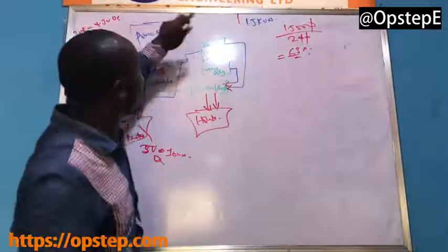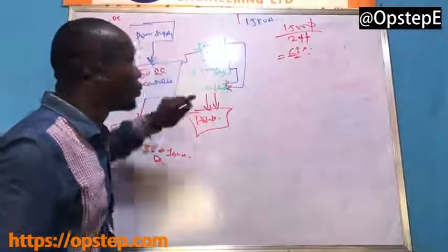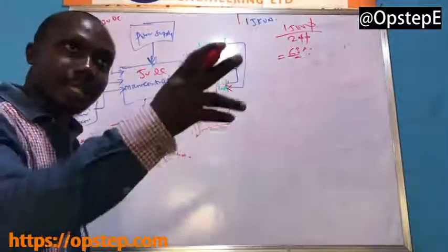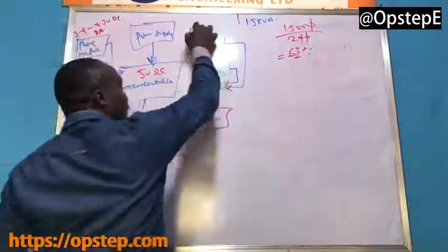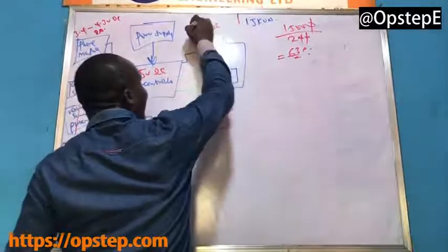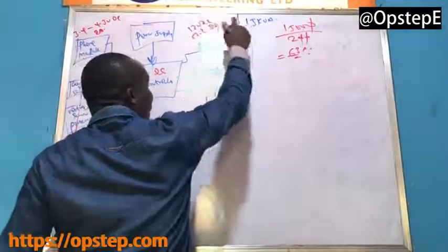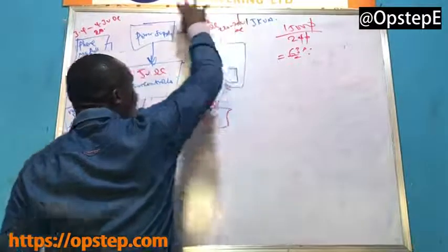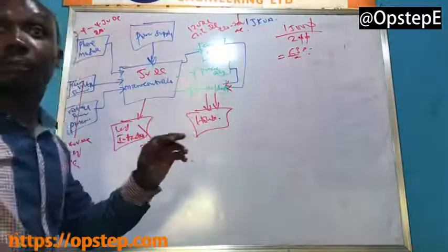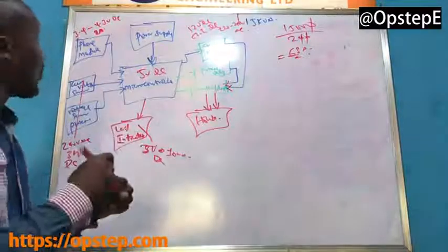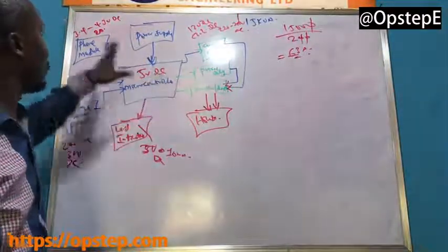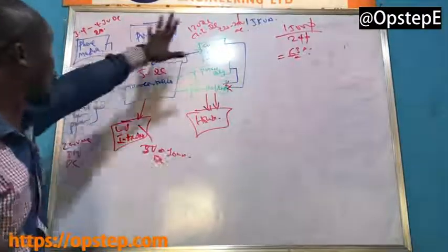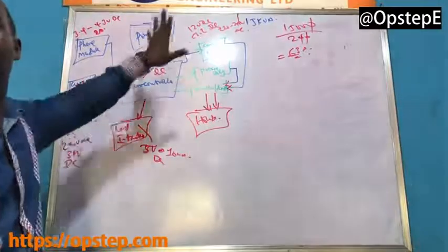For your generator relay, your NEPA relay and the enable relay, it uses both AC and DC. The coil is DC at 12 volt DC, while the contacts are switching between 220 to 240 volt AC. So we'll discuss that. Are you following me? Now, we haven't been given these details.